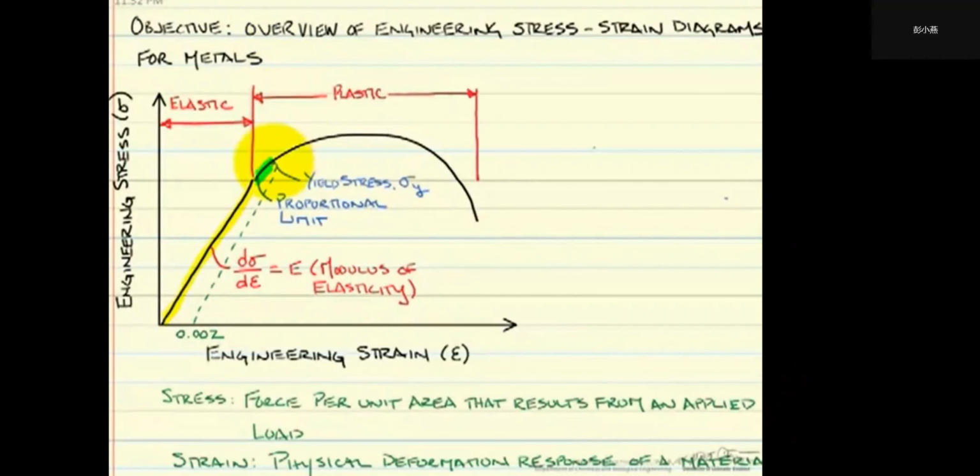With additional force, the test specimen will eventually begin to neck. Or rather, the diameter or thickness of the specimen decreases in size. We call this point the ultimate tensile strength, or UTS. This is the maximum possible engineering stress that the specimen can take in tension. If we continue to load our specimen with additional force, we will find that the specimen will eventually fail. At this point, our bonds have completely broken. As we did with the yield stress, if we want to understand the engineering strain at fracture, we need to unload parallel to our modulus of elasticity line.